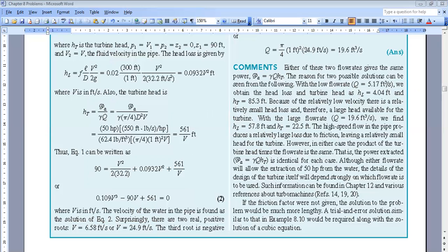Any question on this problem? In real life, which one do they tend to use? Look, sometimes it will depend. Of course, if you can go with small velocities and reach the same solution, it's fine. Because you can always have unpredictable losses. Like here, we neglected the minor losses. So if you take them into consideration, this might lead to a lower power. This is why you can work with the smaller velocity, because if you have minor losses, they will be reduced with a smaller velocity.